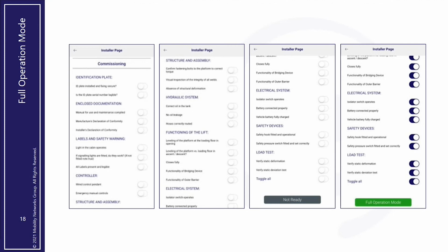We put the lifts into safety mode in the factory. You can think of safety mode as some sort of limp mode that is found in vehicles. In our case, it delays the deploy operation of the lift by 10 seconds and activates the buzzer. If you don't want to use the app, you also have the option to use the hand control, but it won't reset the service date or the cycle counters.